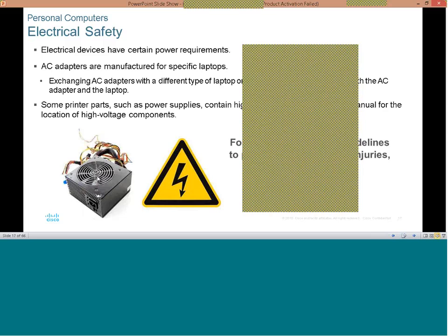Sometimes if you open the power pack, just to add more information, some of them just have a small fuse there with a tiny wire, and the fuse might just be 6 amperes, in some cases 3.5 amperes. So if there is a surge on the electrical line, the fuse might just cut off. That's safety. You can get another fuse of the same amperage, put it there, and then your power pack is back again.